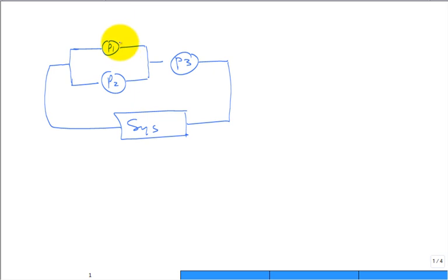For each of these pumps, they give the specs. So pump 1 is a 1 by 1.5 by 8 inch pump running at 3,500 RPM with an 8-inch impeller. Can you find one of the handouts that I gave you for that pump?